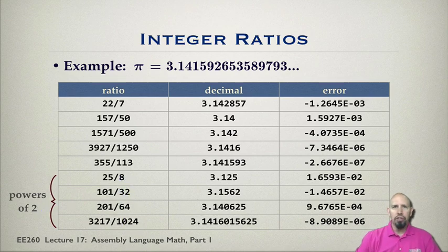Remember, powers of 2 are nice because when we do the division, it can be just a shift. That's really helpful. Actually, all of these would be shifts. So I would multiply by 201, and then I would do shifts associated with this. This would require 6 right shifts. The question is whether that's accurate enough, or this is accurate enough. These are some issues that we need to work with.